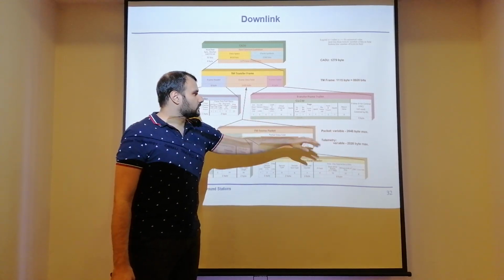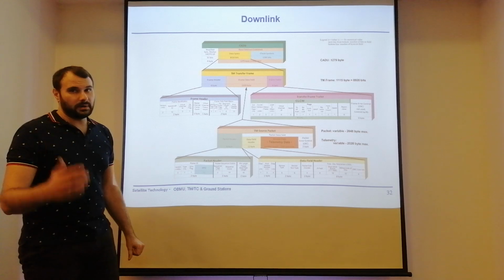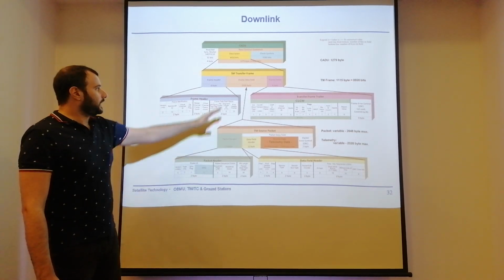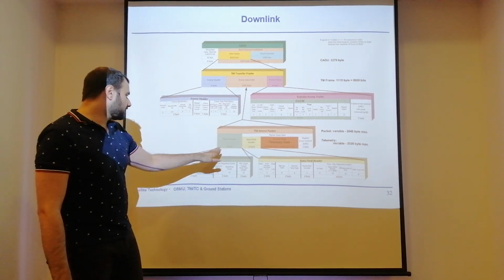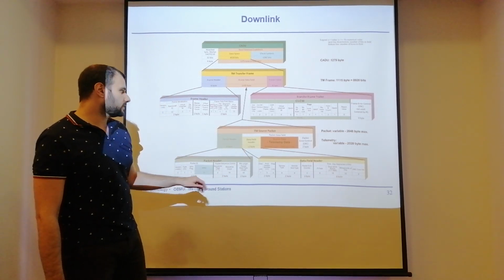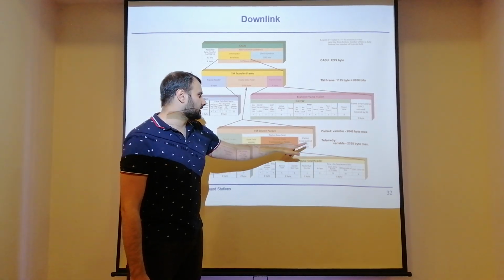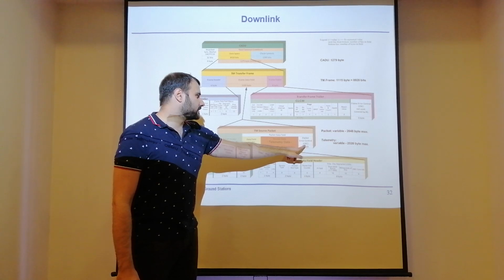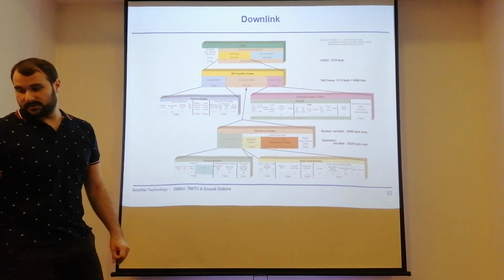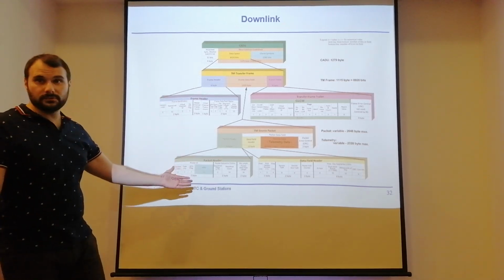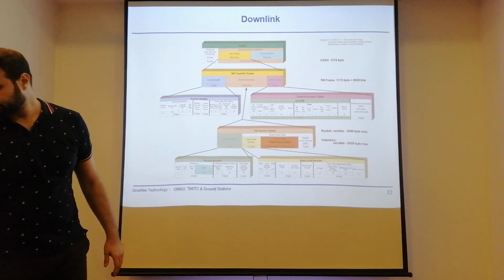And the frame trailer also has some other flags that can be used or might not be used in your case. And if you go down to the frame data field, you have the TM source packet that has another packet header with a packet counter, a data field header, and your telemetry data at the end with the CRC, so with your cyclic redundancy check symbols. So this is an example for the CCSDS communication.